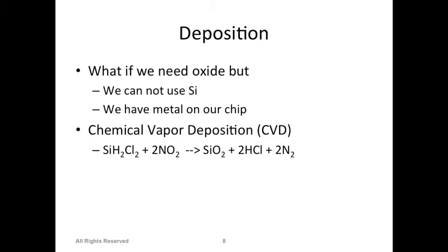Then there is CVD, which is chemical vapor deposition. Basically you have fumes or precursor gases which react on the surface, and you have a thin layer deposited after the reaction. But those two gases will not react all of a sudden by themselves. So basically you normally have to provide them enough energy so they can start reacting. Okay? So in a CVD, the energy can be provided with the temperature, right?